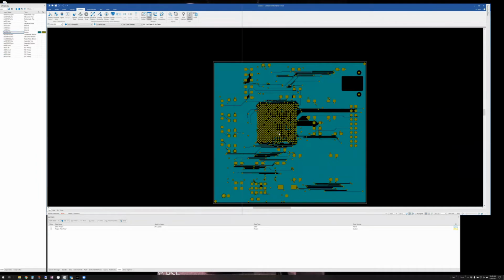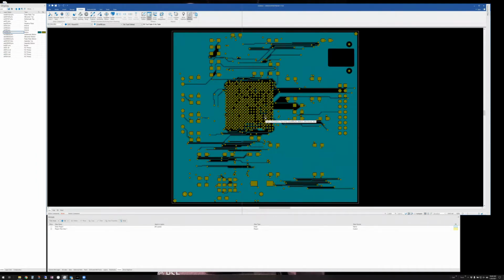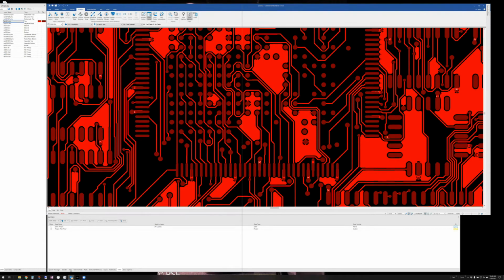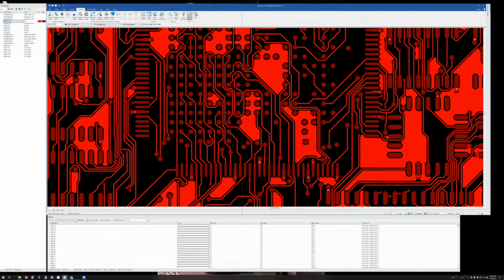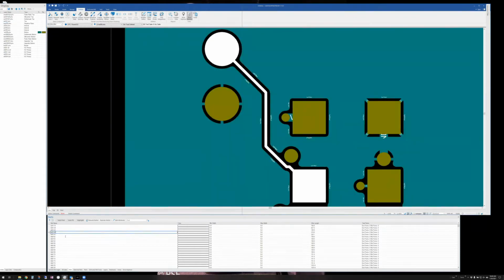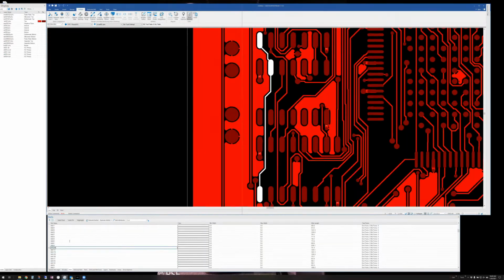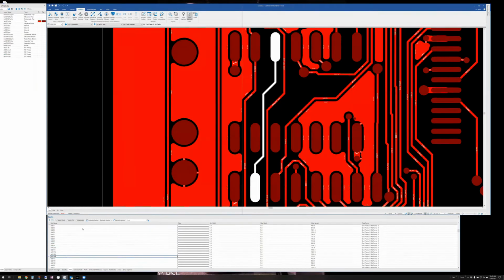So that's a quick overview of analysis and getting to that point, loading Gerber and NC. As we debug certain PCB circuits, we need to see certain signals where it passes to know if it's beside other circuits. So you've got a few choices there. I think probably one of the ones you might use is go out here and find a net, and then follow that net, whether it's something that's real simple like these are, or something that goes through maybe multiple layers or whatever.